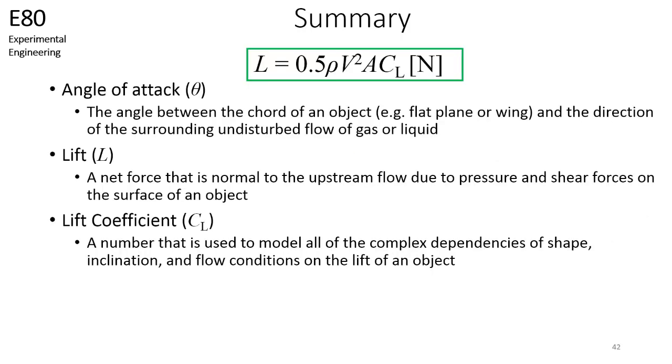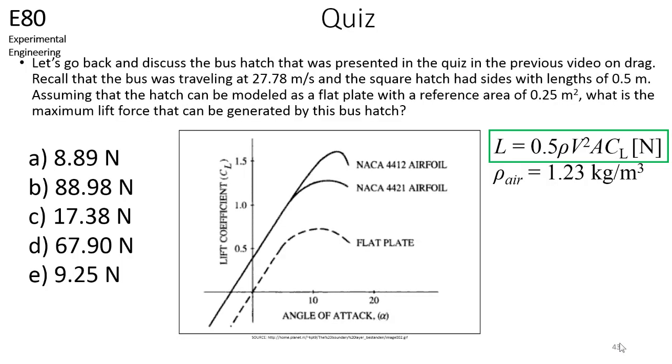In this video, we focused on lift. Remember that the angle of attack is the angle between the chord of an object and the direction of the surrounding undisturbed flow of gas or liquid. Unlike the drag force, lift forces are normal to the upstream flow. Furthermore, the lift coefficient can be used to model all of the complex dependencies on the lift of an object, such as shape and angle of attack. We hope that you think about these the next time you take an airplane flight or watch your robots propel themselves through water. Now let's take a quiz.